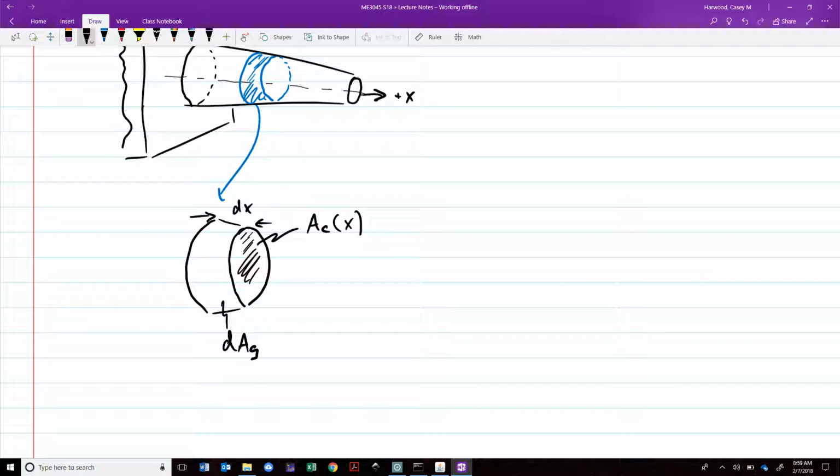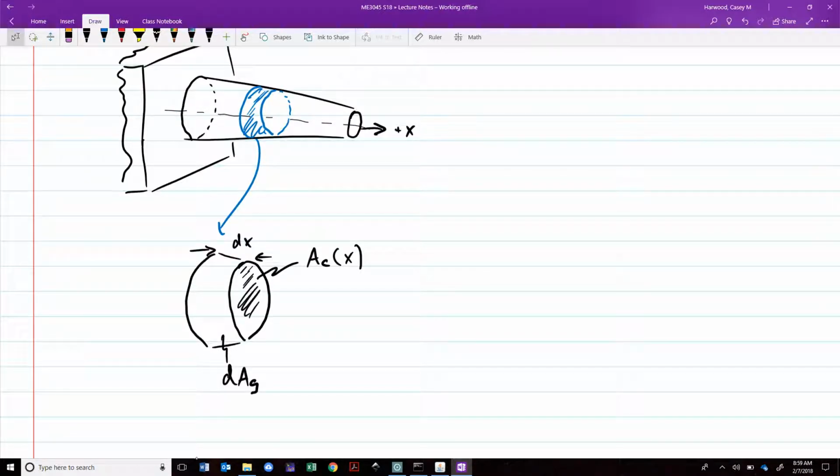So what about an energy balance on this little slice of our fin pin? We've got heat coming in, we'll say this is Qx. We've got heat coming out, we'll say this is Qx plus dx. That's what's flowing through this cross-sectional area. Out through the exposed surface, this region here, we've got some rejection.